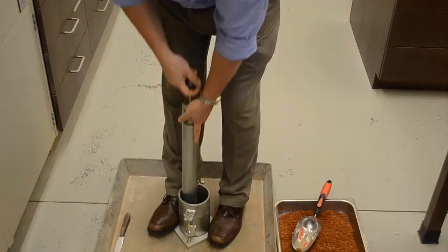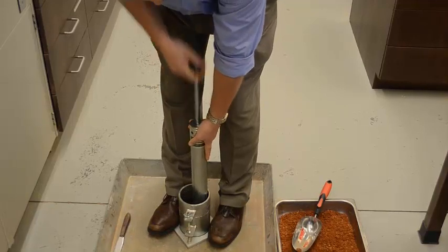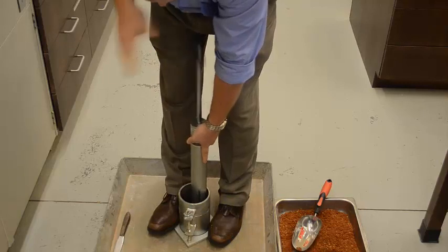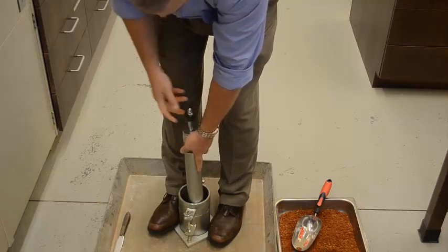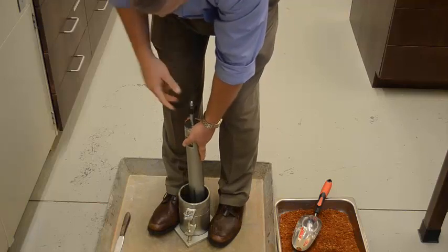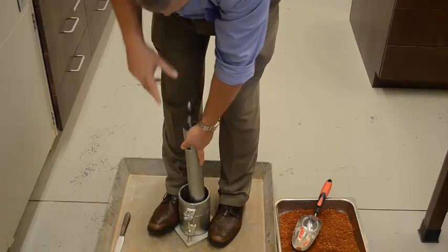Lift it up, move it around a little bit more, and let it drop. Obviously, you're counting the amount of blows, not letting the material get stuck in the collar. And you do this around in a circle 25 times, making sure that the mold does not move anywhere. And that's why I keep my feet on it.